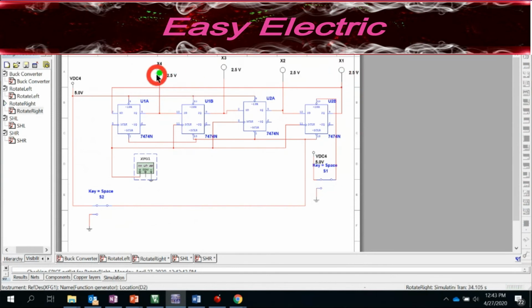So see, it moves here, it should be shift right, then it moves here, then here, then here. Now see the rotation. Now it should be back here with the rotation, okay? It's back here. So that's the shift right with the rotation. It's here. Next should be here. Next should be here. Unlike the shift right, you are not losing that. So then on the next rising edge it rotates to the beginning of your shift register, okay?